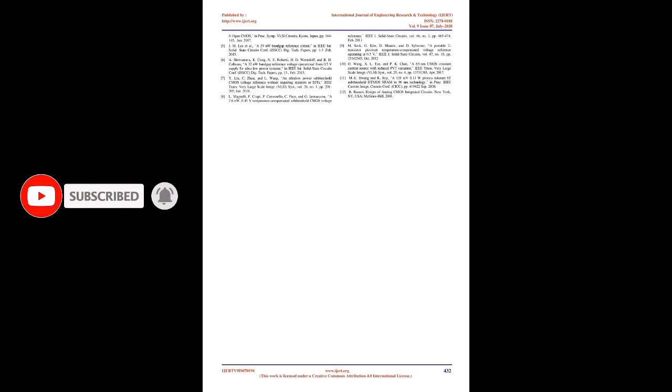Fig 3 shows the simulated output voltage measured against 0 V to 2 V. Fig 3 also shows the simulated output voltage measured with temperature variation from -20°C to 140°C. The generated Vref of the proposed sub-BGR is 248 mV and is also associated with the PTAT term and the process parameter. The PTAT term is not constant in an actual system and depends on the capacitance of the gate oxide and depletion layer. Still, the variance is not too large.